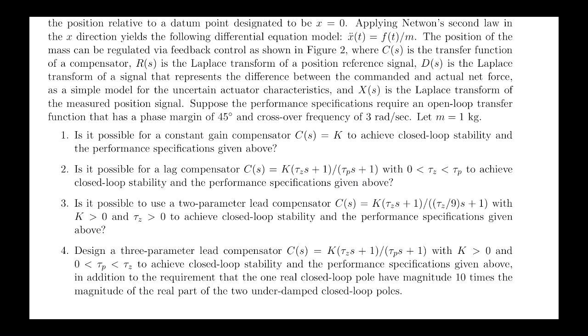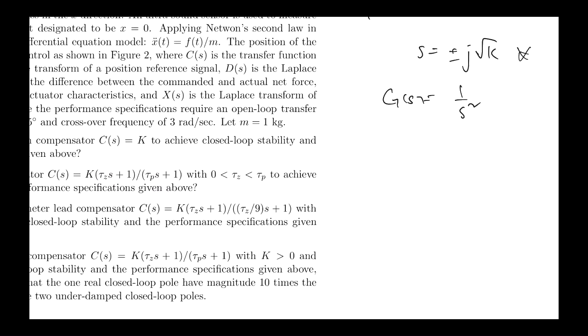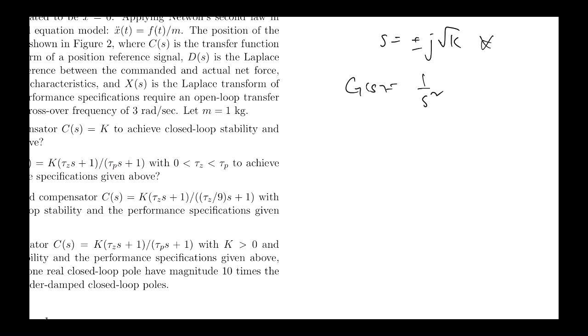If you drew a root locus type plot, we'd still have the two poles at s equals 0 from the plant, and we would have another one due to the controller and a zero that is further away from the imaginary axis than the pole due to the compensator.